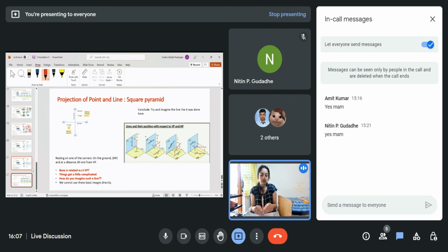That plane thing will come later. I'll try to explain that also in the next live lecture, but here you need to understand, if you have a line, you rotate it first with HP, you'll go like this in a cone. So you'll be actually rotating the projected length in the top view and get the projected length in the vertical plane. Or you can first make an angle with VP, then you have a cone like this, and then you rotate the projected length in the VP by 60 degrees, because we have taken the example of 60 here, so you rotate it by 60 here.